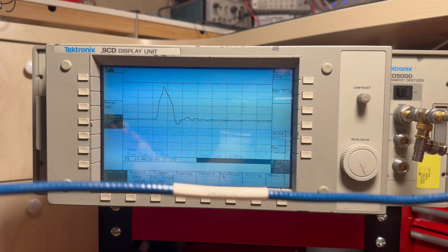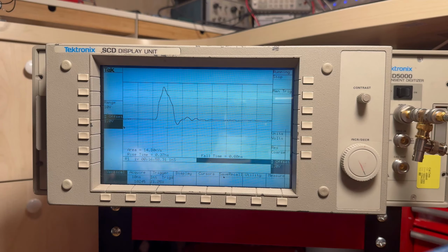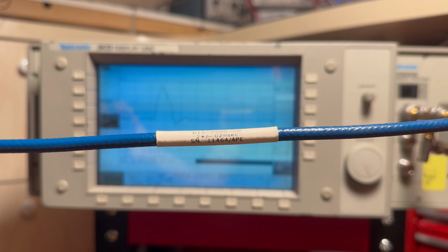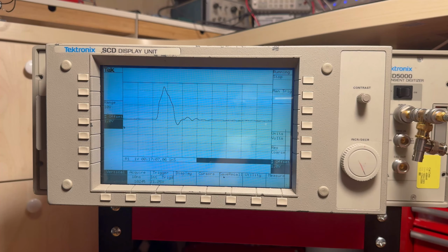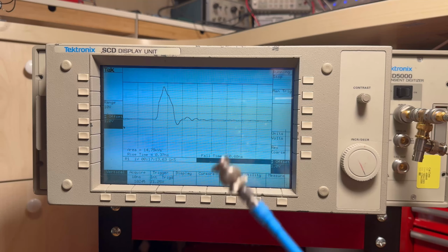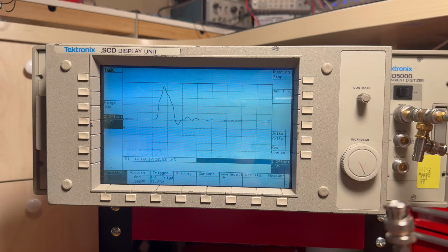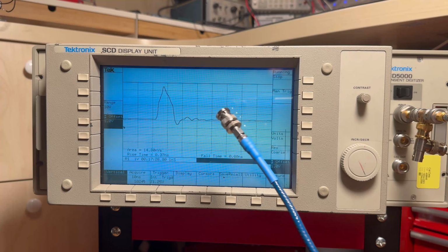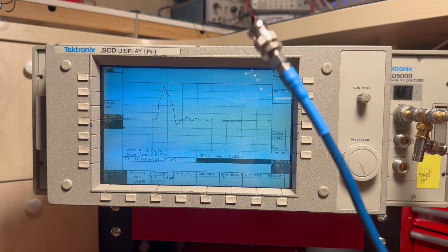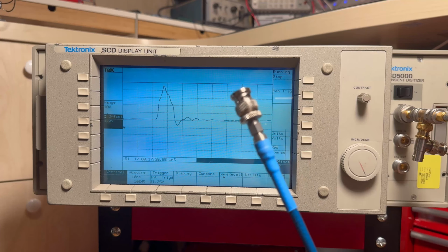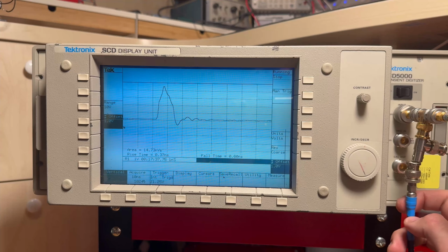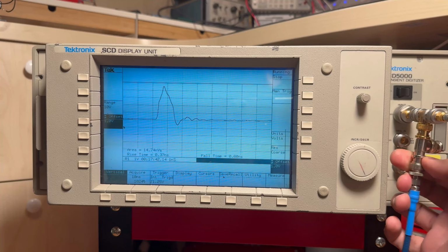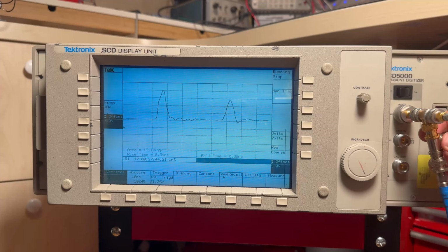What I have here is the cable that went from the input to the scan converter tube, and this is 2 nanoseconds long. So in particle physics usually, and in research and in RF as well, I think cables are specified by their length in propagation time. So this is a 2 nanosecond cable, which is about half a meter long because it's 4 nanoseconds per meter. But the TDR will show us the to and fro time, so the round trip time. So we should be looking at around 4 nanosecond return trip time. So if I connect this here, we should be looking from leading edge to leading edge, and I hope I can kind of put it like here.